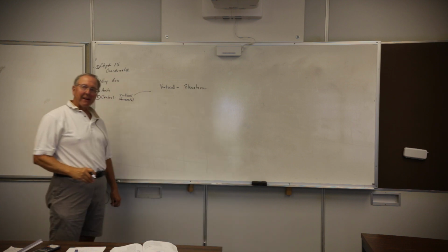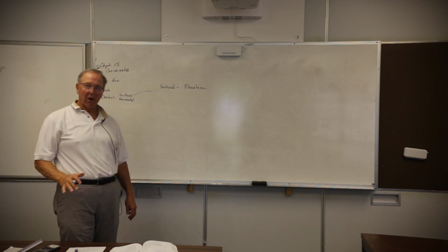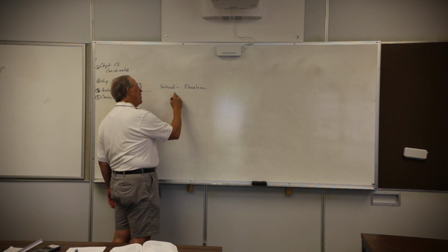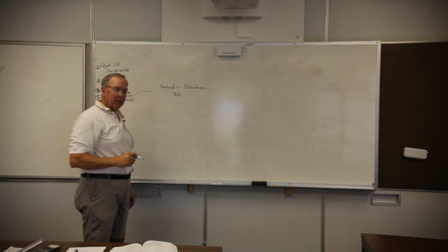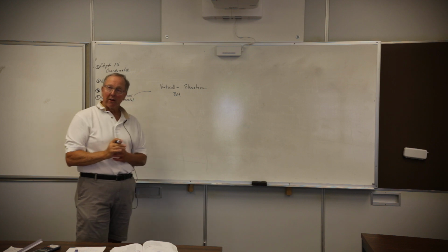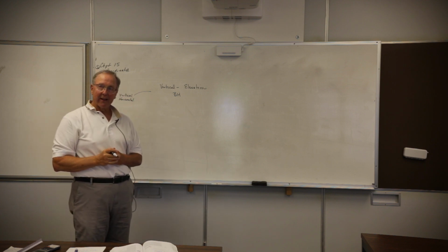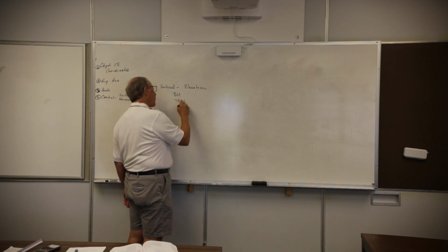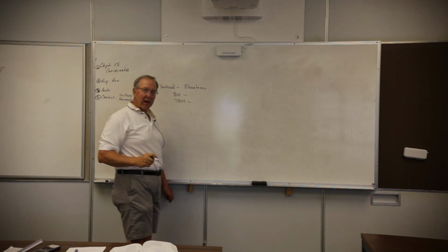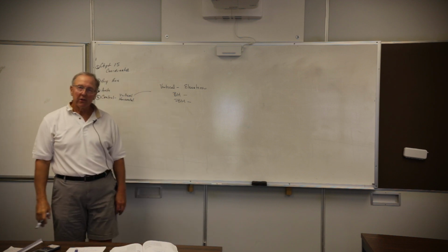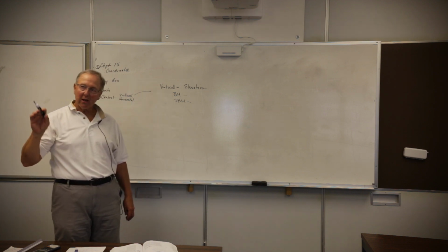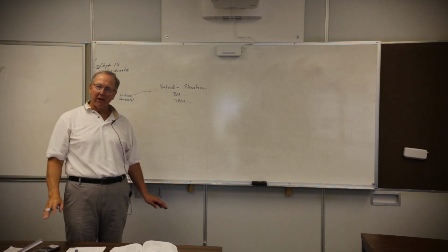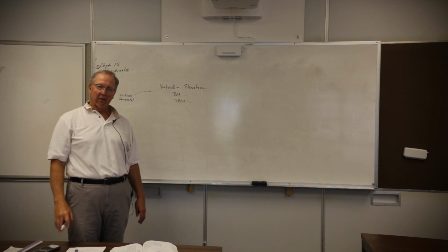The elevation is going to be indexed to some type of benchmark. We talked about that before. The types of benchmarks are going to be a USGS benchmark, which is the United States Geological Survey benchmark, that indexes to the world, or a site benchmark. A site benchmark is indicated on the drawing by the design team, and you'll know exactly what object on the site is at what elevation, and then you'll index everything you do off of that indexed elevation.